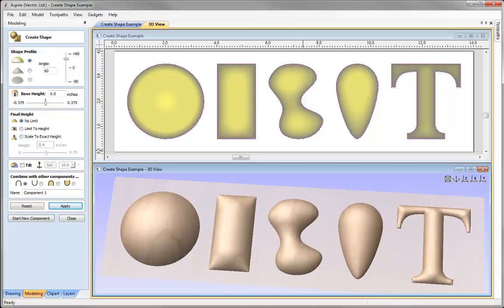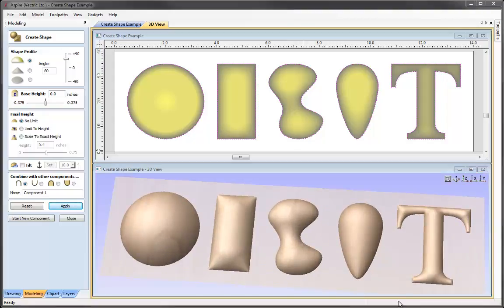And we can see that shown in this shape here. So if we just zoom in there, and if we take a look at the bottom area here, when I move my cursor over the top of this shape here, we can see that the Z height is around 0.35, and remember this is the wider area here. And then as I move that cursor down where the shape is getting narrower, we can see that the Z height is getting smaller. So we can see there it's at around 0.19.